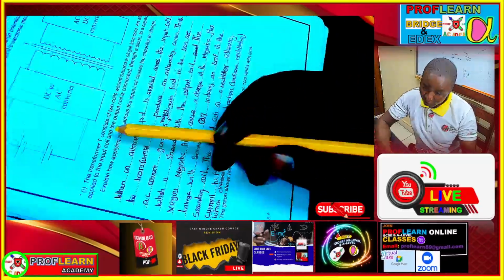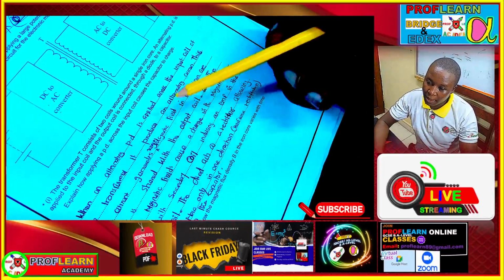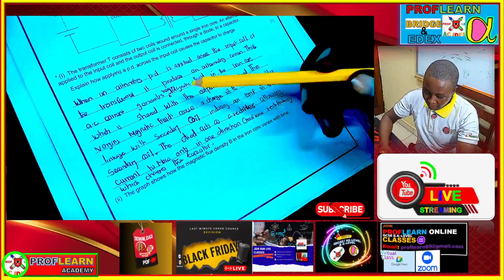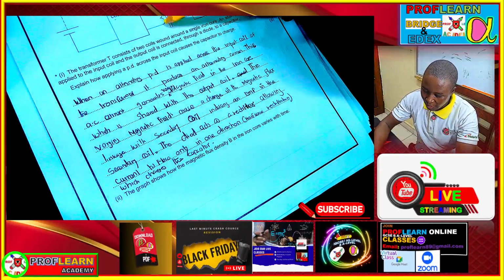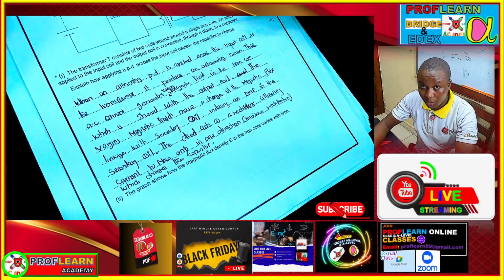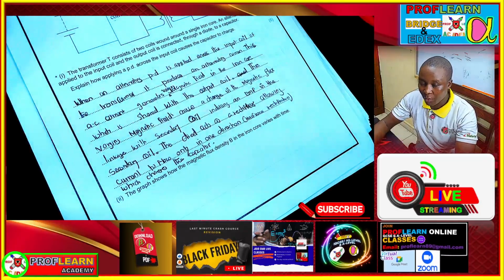The transformer T consists of 2 coils. Explain how applying a PD across the input causes the capacitor to charge. So remember, when the alternating current passes through here, it is going to create magnetic fields in this section, and those magnetic fields are going to be linked to the secondary coil, which is going to result in a magnetic flux linkage. When there's a magnetic flux linkage, there will be an induced current. So the output coil then